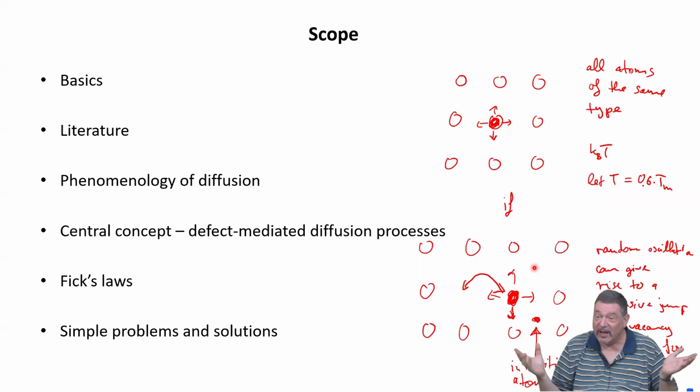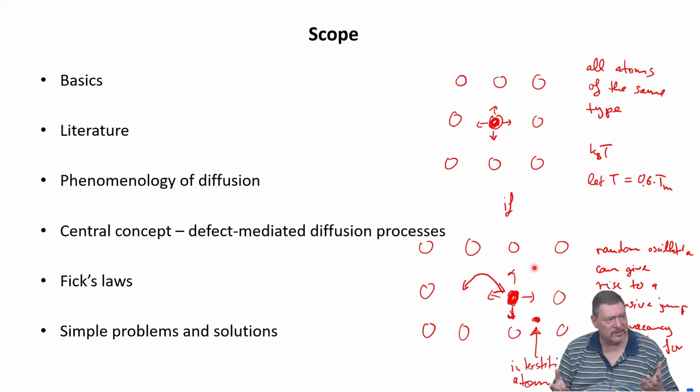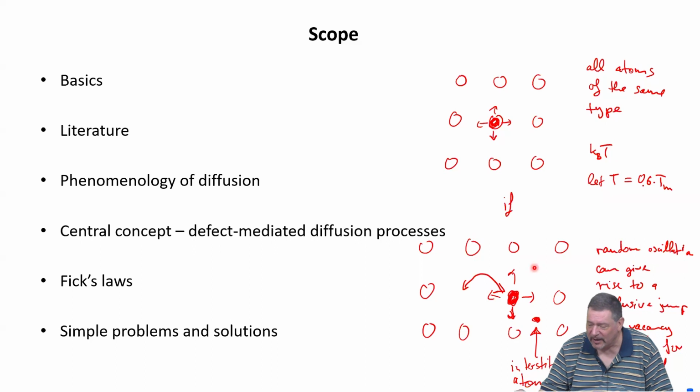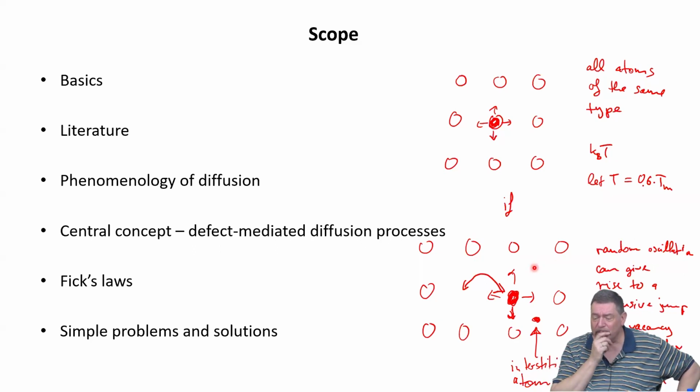So this is why we have all these problems with hydrogen in steel, because it goes through steel like a bullet through butter, right? It's really fast, and unfortunately it even embrittles the steel when it goes through. But you also cannot keep it, because the diffusion process is so quick. So this shows you in a small discussion that diffusion has different aspects.